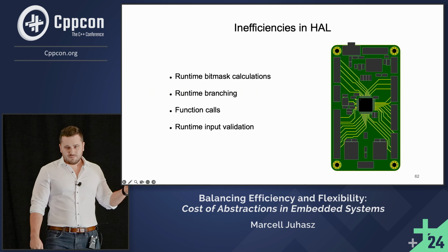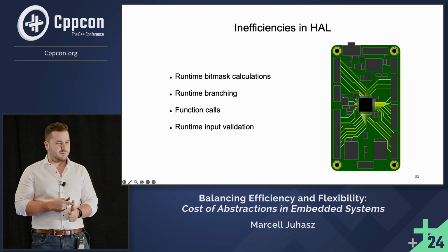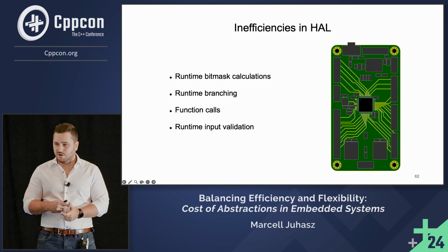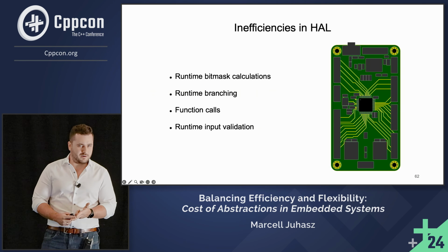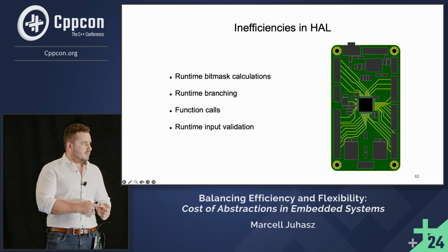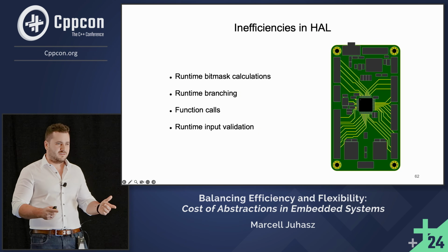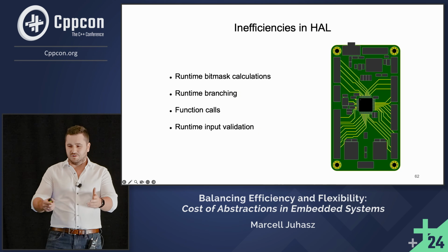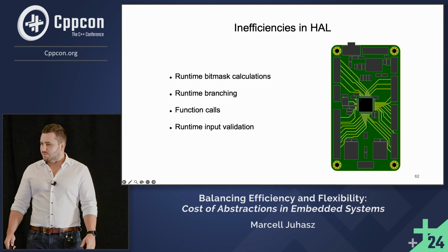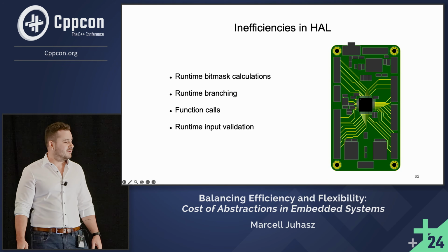So when you are developing firmware for a project like this, you probably already know which pins will be used as GPIOs, which ones will be ADCs or part of an I2C communication bus. You probably already know the resolution of the analog digital converter. You know the frequency of your I2C bus. You know the address of the devices on the bus. So there are a lot of things that could and should be known about these kinds of projects at compile time.